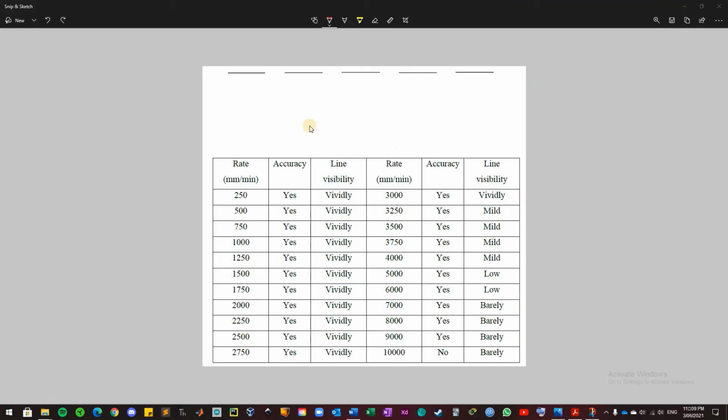As part of the results section, a small test was conducted to determine the maximum rate at which the x-axis and y-axis could travel while focusing on the accuracy. A set of 2 cm lines were drawn with a 1 cm interval between each line. This will determine how fast the pen can move up and down while maintaining speed and accuracy.